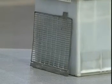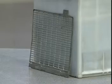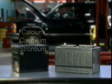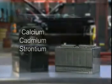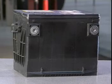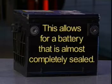In a conventional battery, the grids are made of a combination of lead and antimony. In maintenance-free or low-maintenance designs, the antimony is reduced or eliminated and replaced by calcium, cadmium, or strontium. On a no-maintenance battery, antimony is eliminated altogether, and since no water is lost, the need for filler caps is eliminated. This allows for a battery that is almost completely sealed.